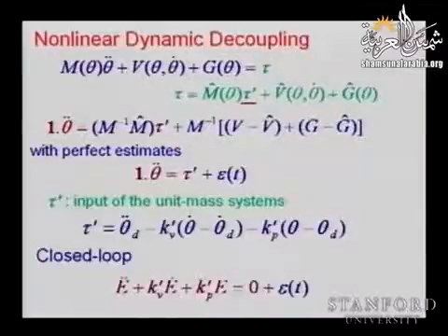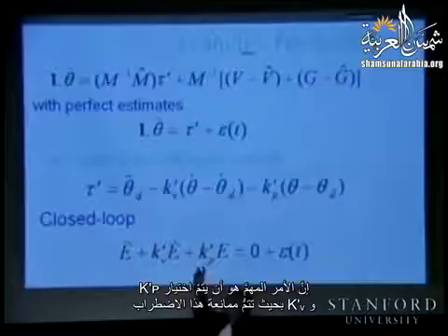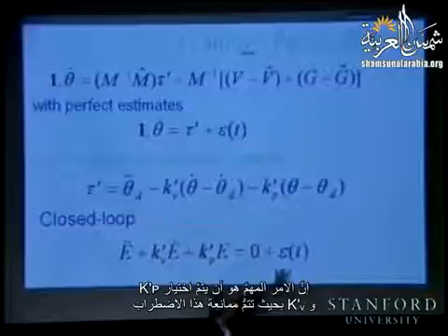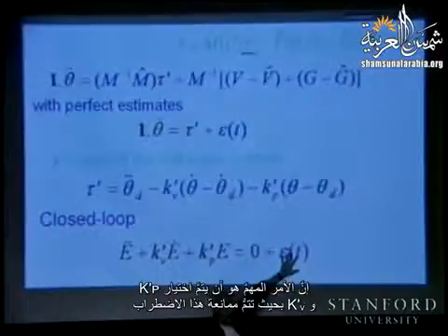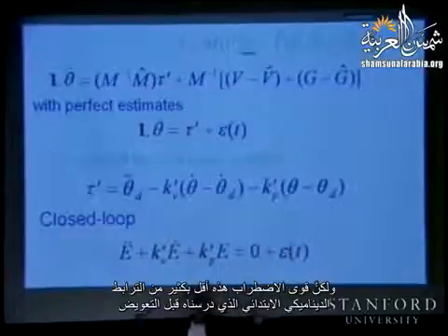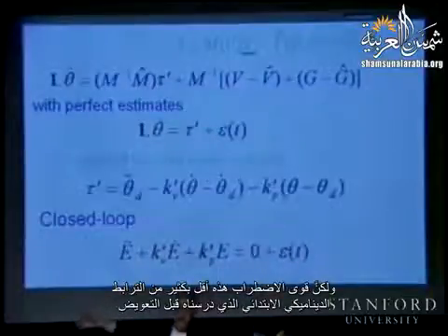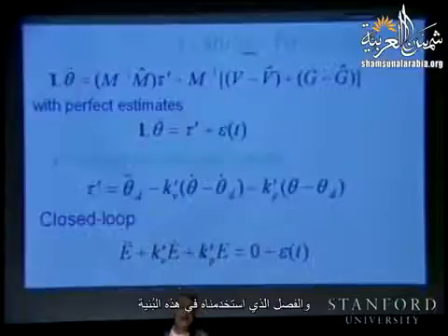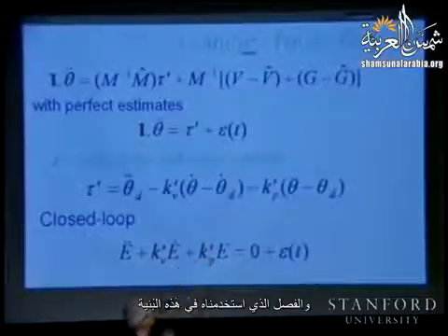So what is then important is that your Kp prime and Kv prime are selected so that you reject those disturbances. But those disturbances are much, much smaller than the initial dynamic coupling that we saw before the compensation and decoupling we use in this structure.